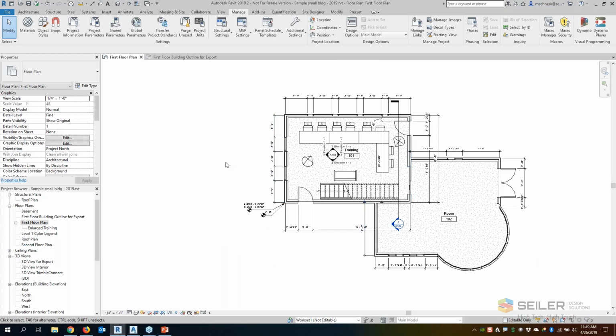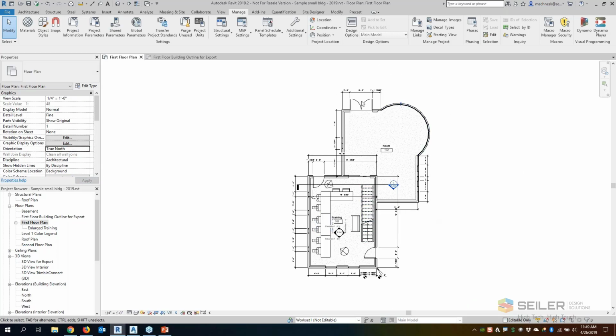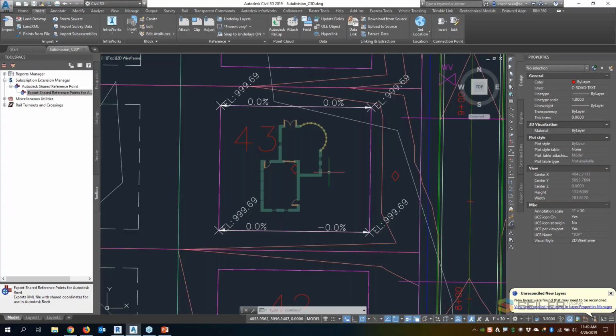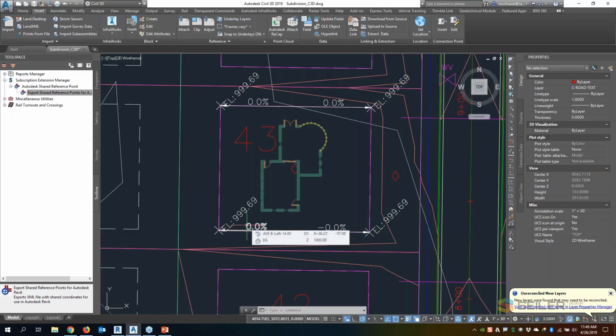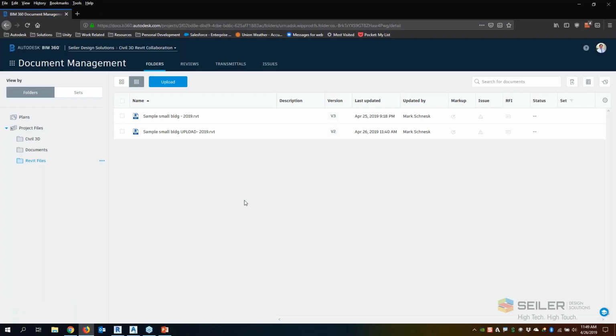And then for any view here, if I'm in a plan view, I'm given the option under my properties window to change the orientation. Instead of project north, I can now change that to true north if I wanted to, and my model rotates to mimic and match the true north layout conditions of my Civil 3D model. Once I've done that, I am now able to export my surface up to the Revit model and bring that in.